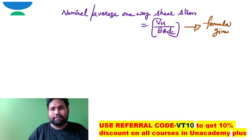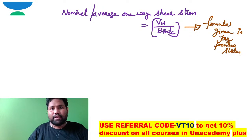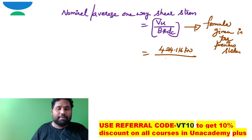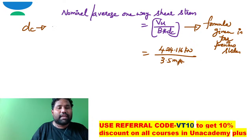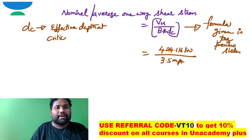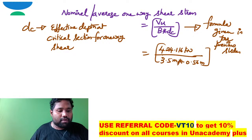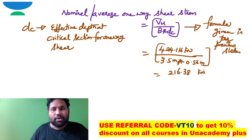This formula I had already given in your previous slides. What is the value of this Vu? 424.116 by b. b is 3.5 meter and the effective depth at the critical section for one way, what is that dc? dc is 0.56 meter. If you work this out, it is definitely 216.38 kilonewton per meter square.